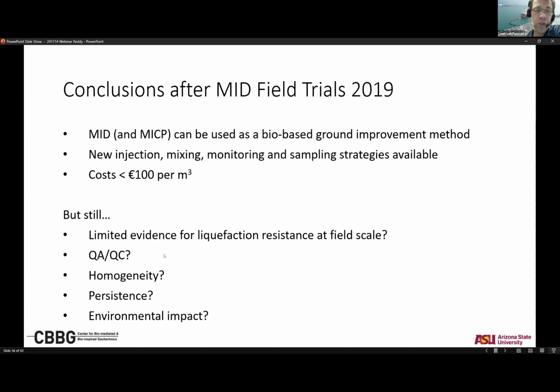So we may still need to develop new theory to predict how the gas would be distributed in different soil types, particularly because soil is relatively heterogeneous. It will probably sit in the larger pores, but then you have to know how the soils are stratified and how they are distributed in order to make a prediction of how the gas is distributed. And once you know how it's distributed, you still have to find out how it would behave under an earthquake.